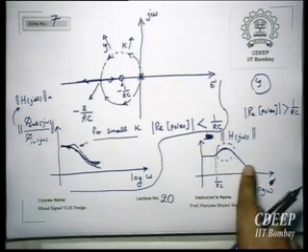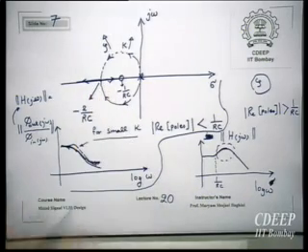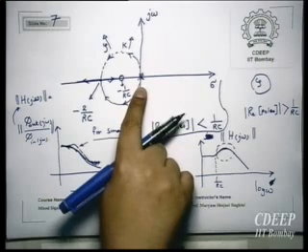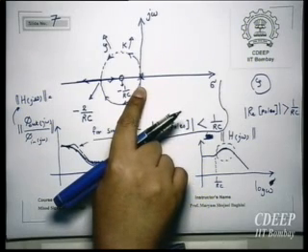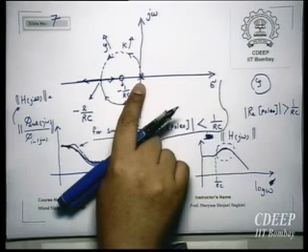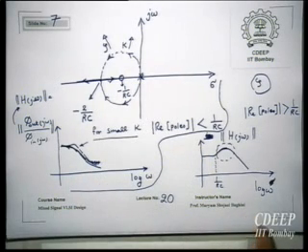Because here your zeta is higher, right? Even if you go under this case, where you have just 2 real poles, your loop will be slower, but it's completely stable compared to this. Because here your poles are close to this real first case, settling time will increase.